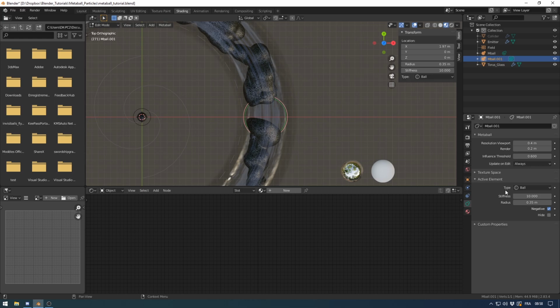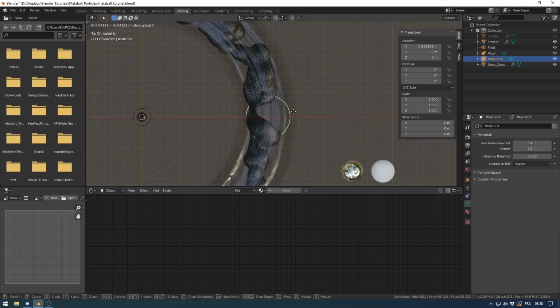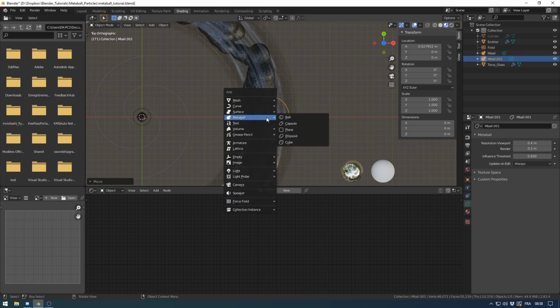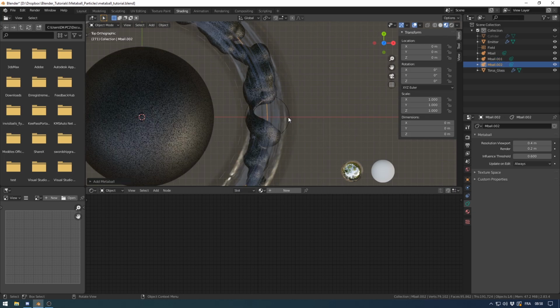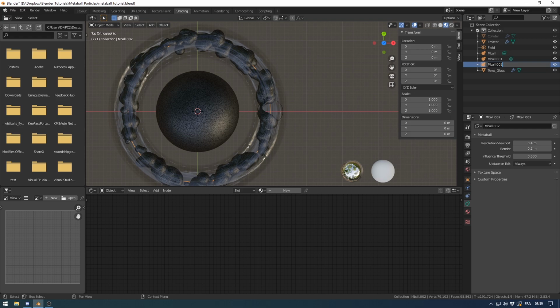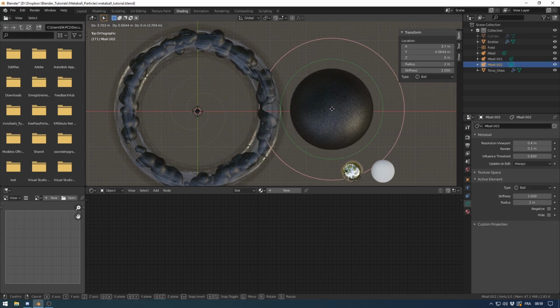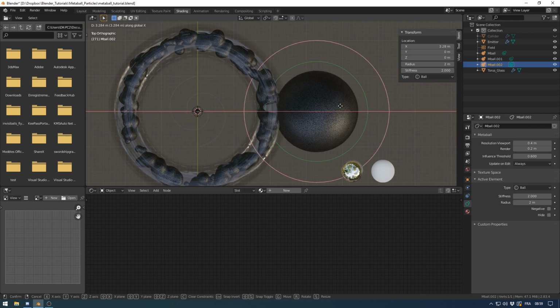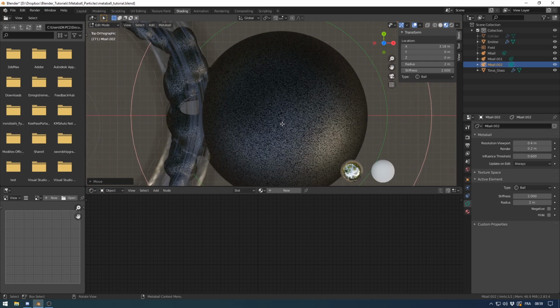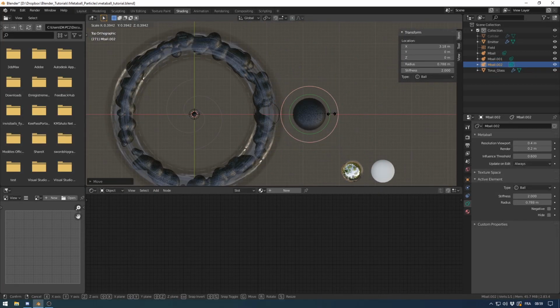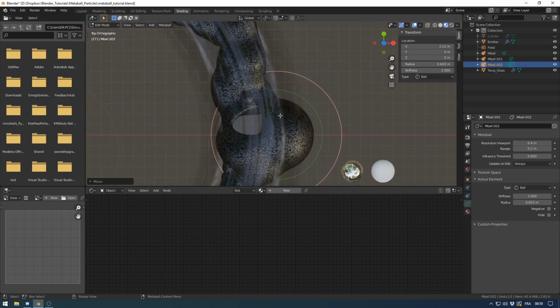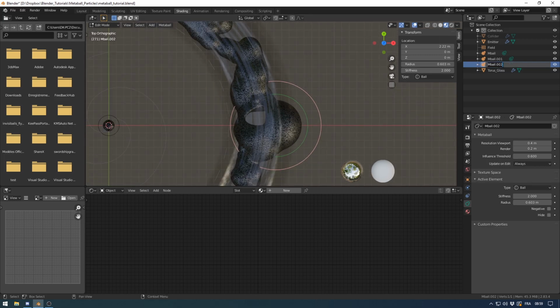Increase the radius to 0.3, for example, and set the sphere here. Okay, this is the same metaball name here, and now I create another metaball, and I changed the material, and I also changed the name, because if you don't change the name, you always have a kind of melt between the metaballs. So you can see that here I changed it to metaballs underscore needle, for example.